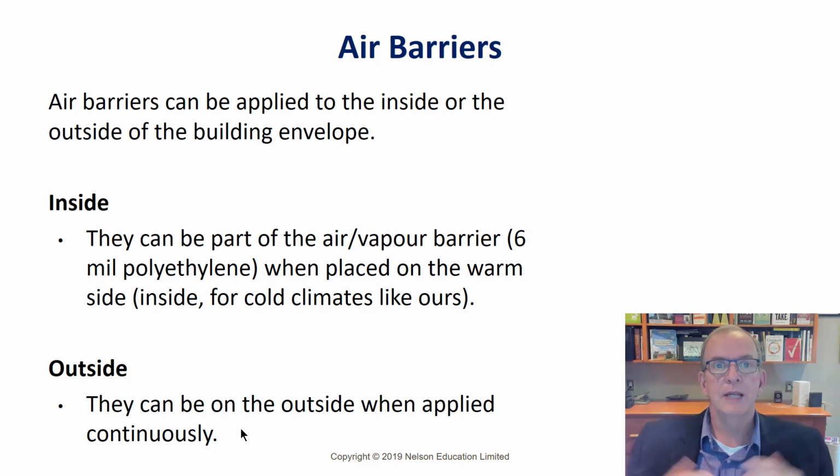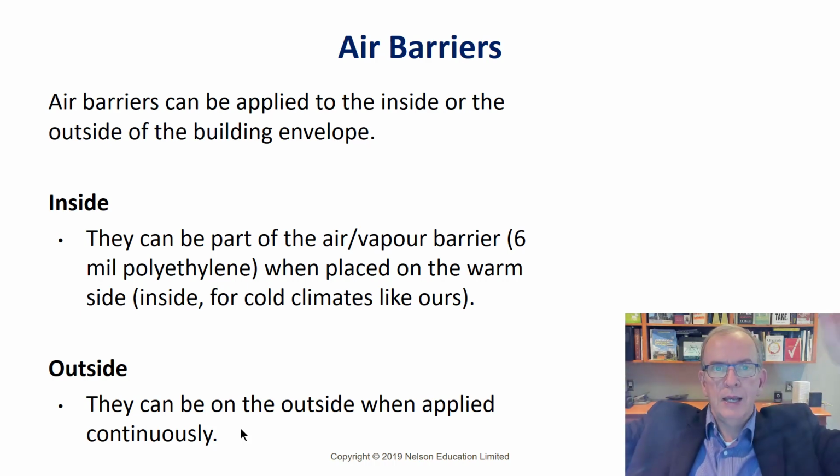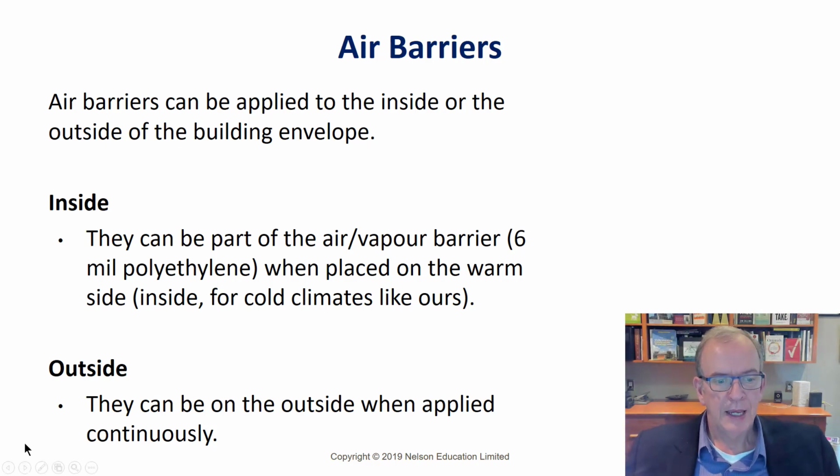So if you've got, for example, a Tyvek or a Blueskin approved air barrier material you use on the outside of the building, it has to connect through the plates to the air vapor barrier that you would use on the ceiling, because that's where you would need to put that one. In that case, actually, I think Tyvek has some pretty good details on their website.